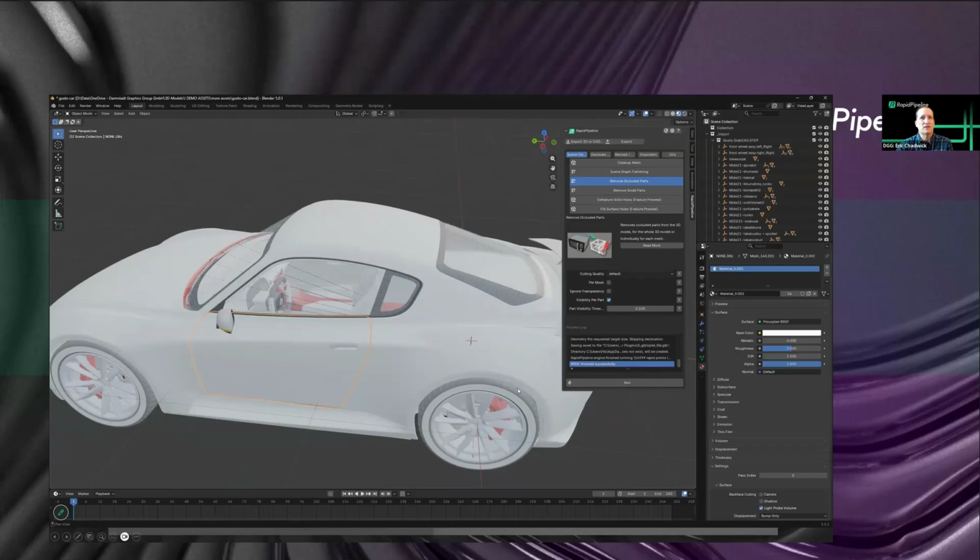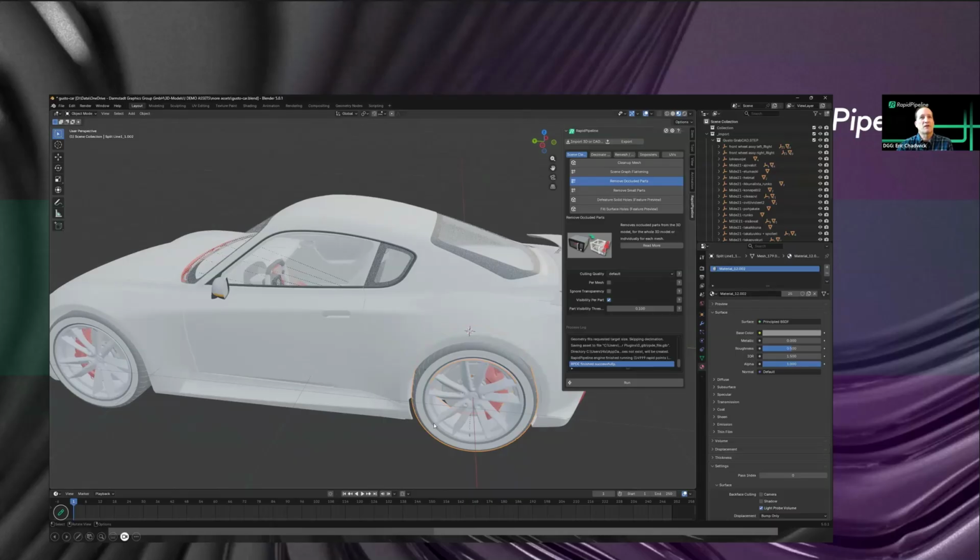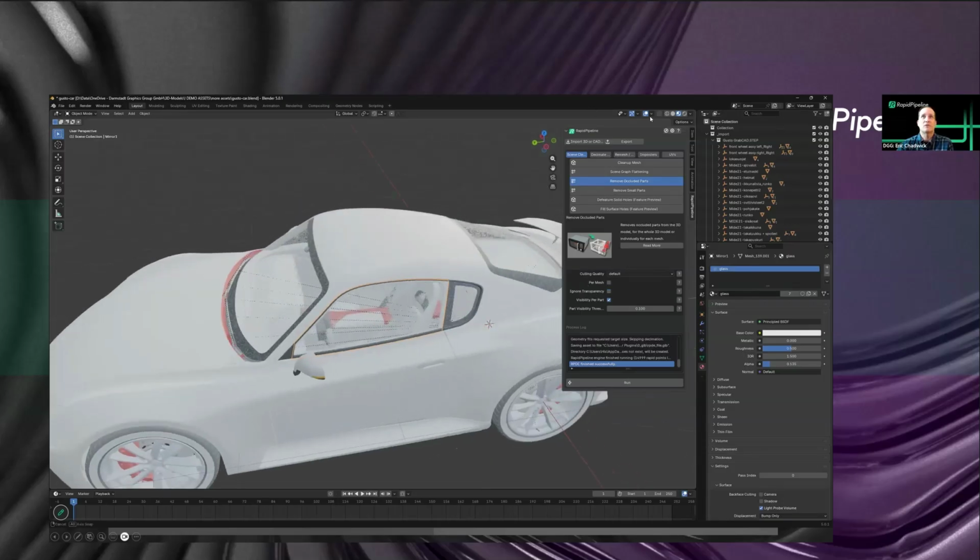That's what per mesh does. It looks at each individual mesh and decides what are interior parts only that are occluded by the mesh node itself. So by default, we just turn that off because I want to do the whole model. And then ignore transparency is the one that would say, hey, I don't care about the glass, remove everything that's inside. So let's just do it without that, the default, and say occlude everything that's invisible.